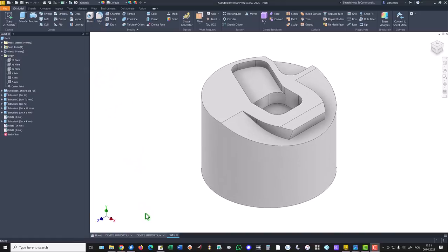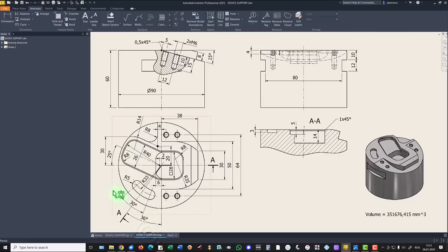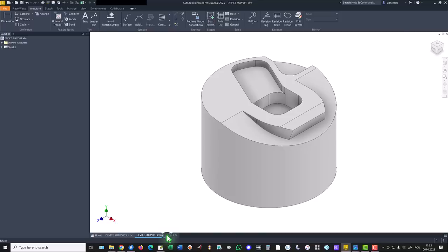Okay. The part has also a curved slot. Here are dimensions. 36 is the mid line. 30, radius 5, radius 33, and the depth is 3. Let's create this.